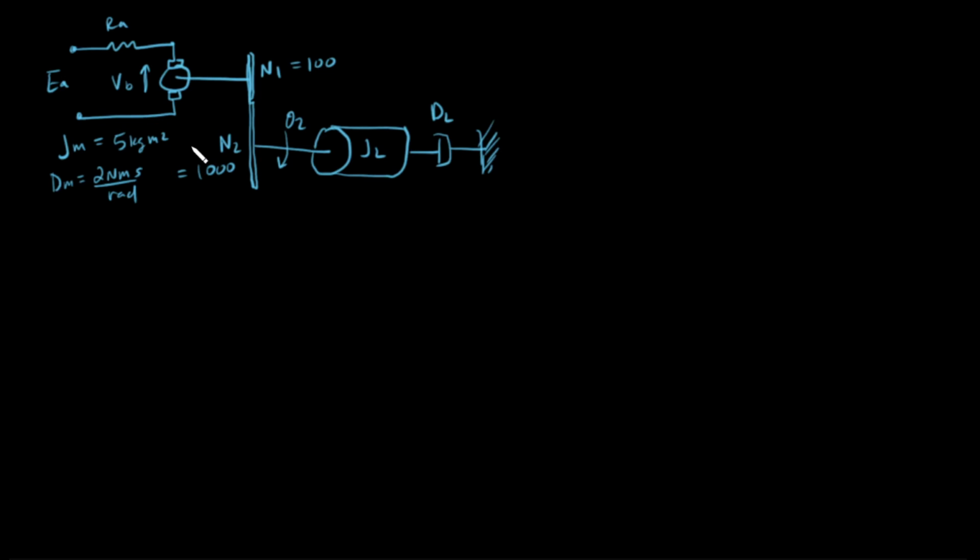And then we'll say first that we get KT and KB, and so let's say that we did a test here, and we found that 500 is the stall torque for this motor, and that 50 is our omega no load. Of course, this is omega, and this is the torque for the motor.